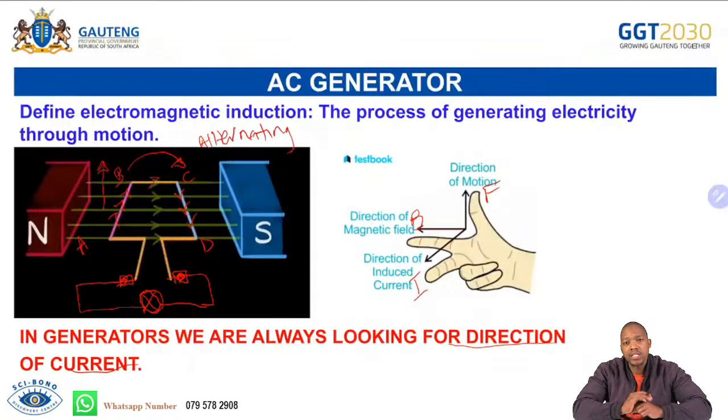So in the internal circuit, we are having alternating current that is busy changing direction. So if we just leave it like this, when B gets to that other side, the current will be changing direction. And that will not work in the external circuit here, because in the external circuit we need the current maintaining the same direction.